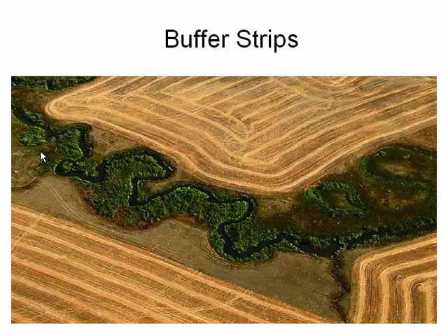Another term for these is filter strips, as an old term, but that was primarily due to their focus on filtering out sediment before it reached the stream. But buffer strips are a very effective and very important best management practice. Not only do they help protect water quality, but they help maintain native ecosystems along the creek and help shade the stream and protect cooler water temperatures where local fish and other aquatic species may require that.